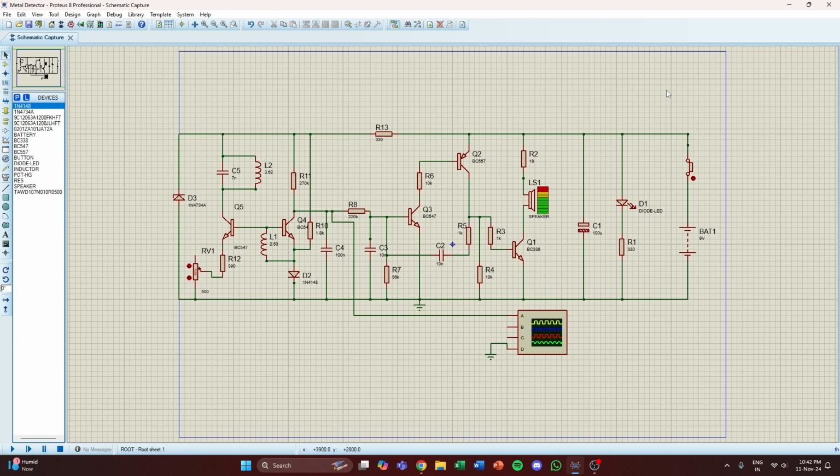The voltage controlled oscillator is a simple, direct coupled high gain amplifier with a 10N feedback capacitor to produce oscillation. When a voltage appears on the base of the third transistor, it turns on, and this turns on the PNP transistor. The voltage on the collector of the PNP transistor rises, and this pulls one end of the 10N capacitor via a 1 kΩ resistor towards the positive rail. The other end of the capacitor is connected to the base of the third transistor. This turns on the third transistor. They keep turning on until both are fully turned on.